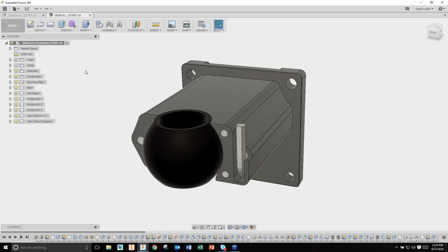Then it's going to ask if you want it to be virtual or if you want it to be its own existing referenced file. That's how those systems are really meant to be used from a bottom-up approach. I'm going to make a single part in a single file, then I'm going to make another part in its own file, and I'm going to bring those two parts together in an assembly. That's bottom-up design.